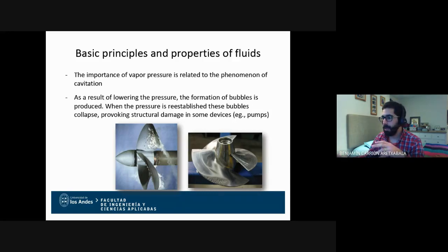And cavitation can be a problem for structures. It actually induces stresses and forces. So it is something that has to be kept an eye on. Also, when you design later on, if you want to design a pumping system, you need to be mindful of cavitation. You can't drop the pressure below the vapor pressure, because your system will start to create bubbles.